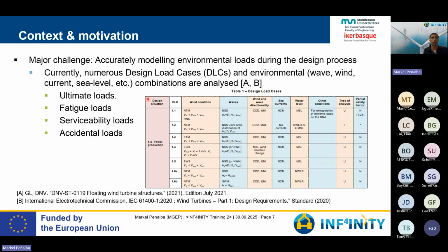So I have only included a picture of 7 different design load case scenarios for the power production region, right? So from 1.1 to 1.6, there are different wind and wave directionality, sea currents, water level, and even other conditions that need to be analyzed.